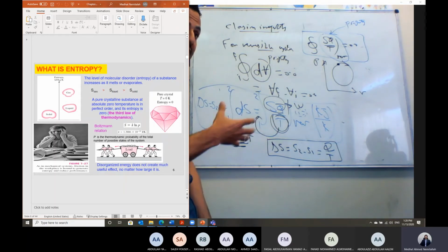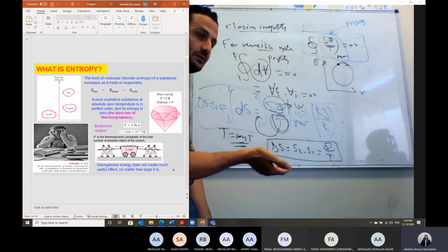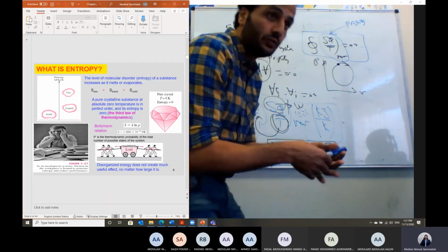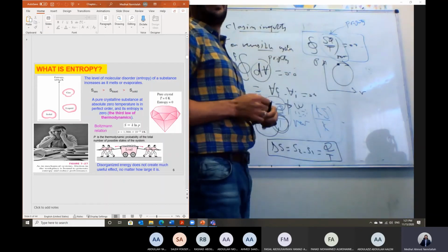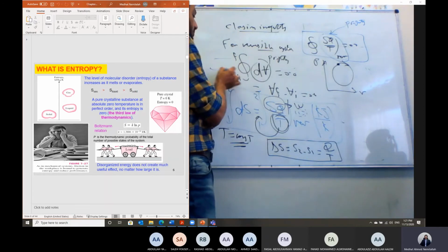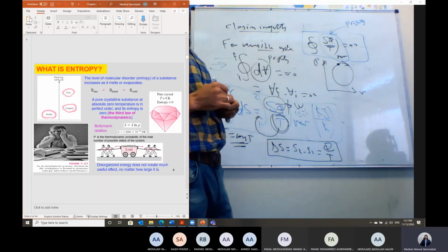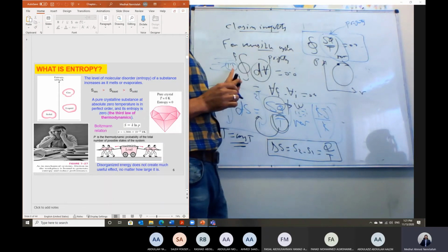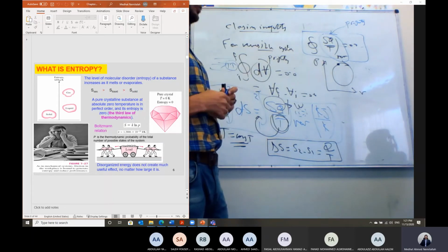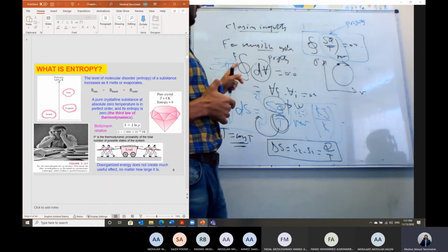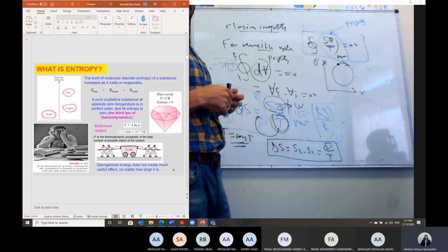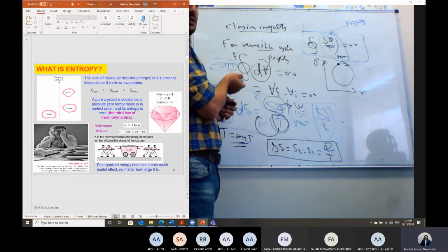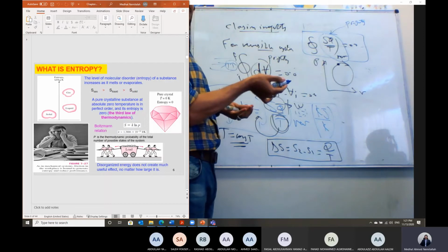system. Because, take the heat dissipated due to friction. Where is it going? If we have a system with friction, let's say a flow inside a tube with friction losses within this tube, the friction losses will appear in terms of what? Of temperature rise of the molecules. The heat will be transferred to the molecules, but the molecules will dissipate this heat in kinetic motion. So we cannot convert the friction losses, in terms of heat transfer, into work.